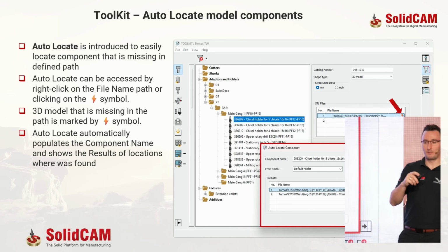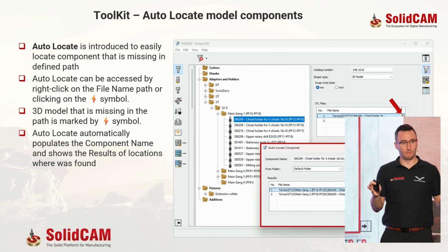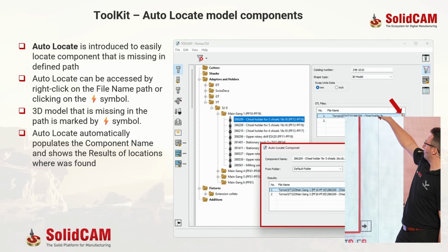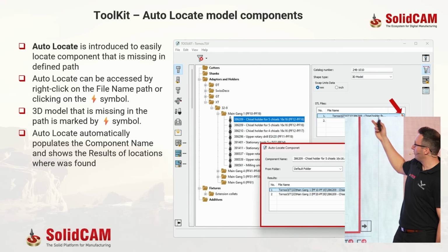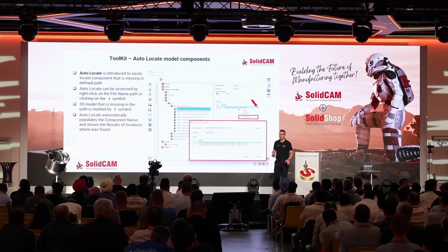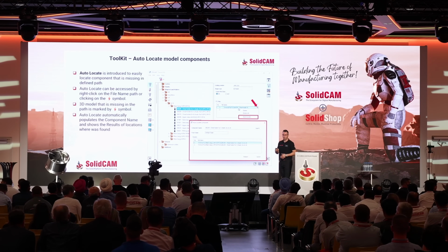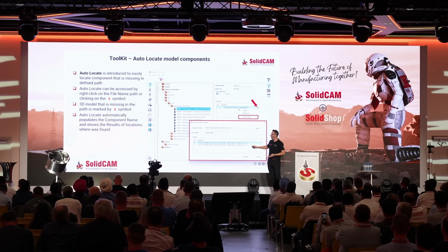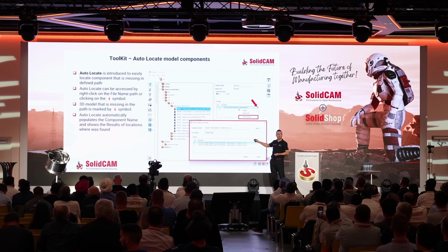So this means that there is no 3D model. The link is broken. So we have a very powerful option: just double-click or just auto-locate, and we are going to give you suggestions based on the same STL name, or you can just find it in another one. Very nice, very useful in the cases when you want to reorganize your libraries, change the links and stuff. We are going to continue to improve even this feature, so stay tuned.